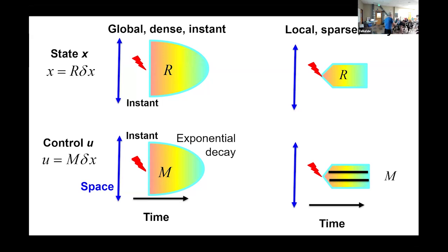So I don't have to be faster than the plant. But if I'm way slower, suppose I'm so slow that I get hit and I sit here and I sit here and I sit here, then it's just running open loop, right? So now there's a trade-off space. How much do you want to stop it versus the communication speed? So now you have a design tool. You can come in and say, okay, comms guys, how much is it going to cost? The actuator guys, how dense do we put the actuators? How dense do we put the sensors?